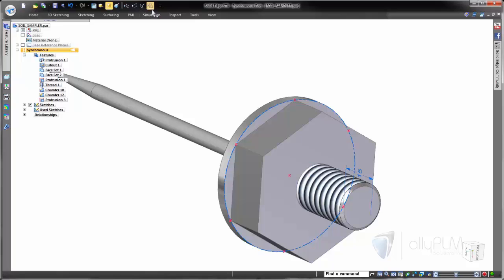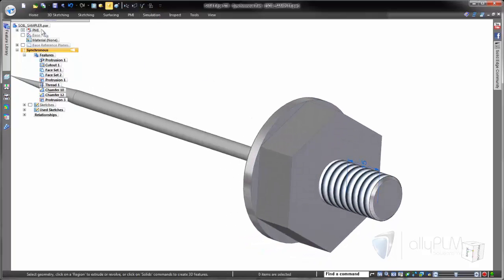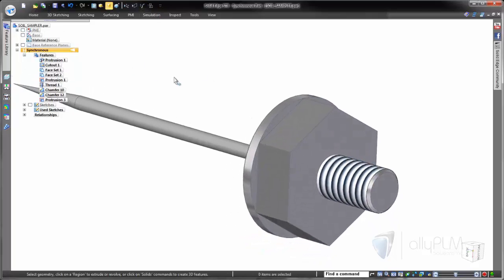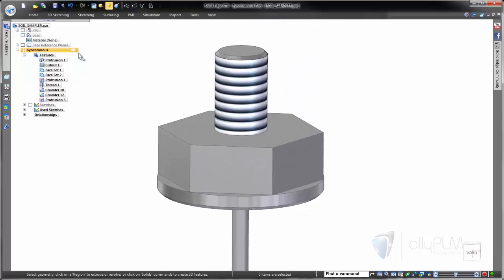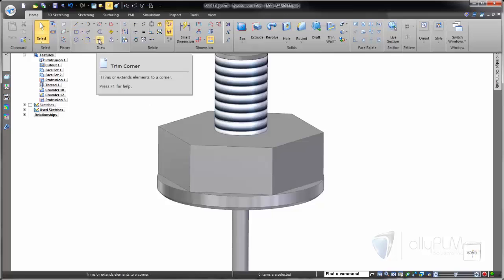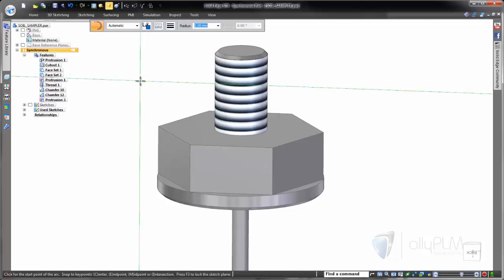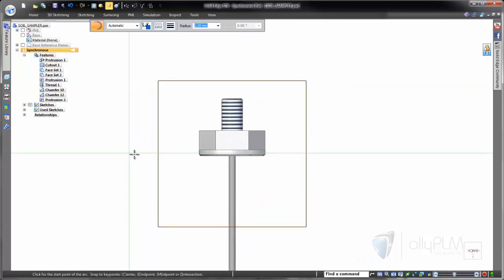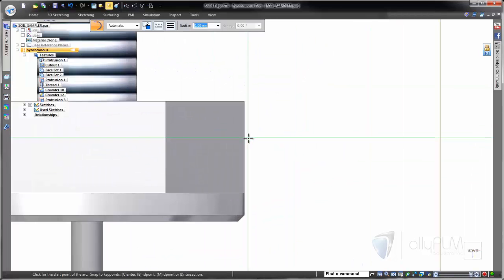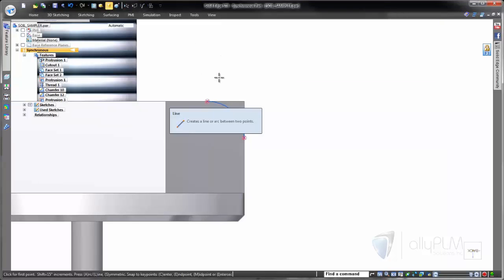In this particular case, we want the hexagon to be inscribed within the circular edge of the probe base. Setting the option to create by vertex makes this extremely easy, resulting in a region that can be dragged to create a hexagon feature. The sketching tools inside of Solid Edge also make it very easy to define a quick revolve feature to cut away sharp corners on the top of our new hexagon feature that will serve as the base.